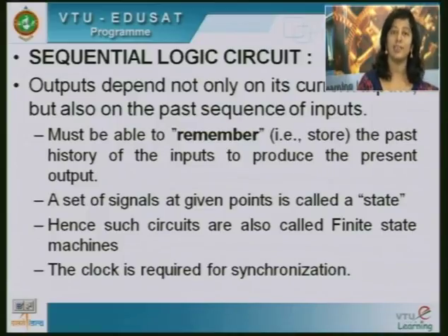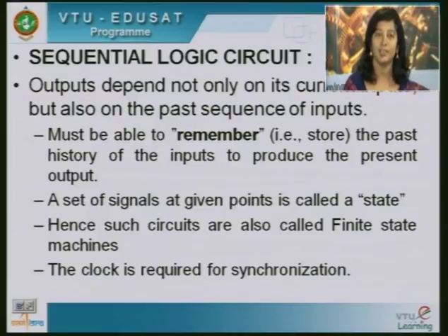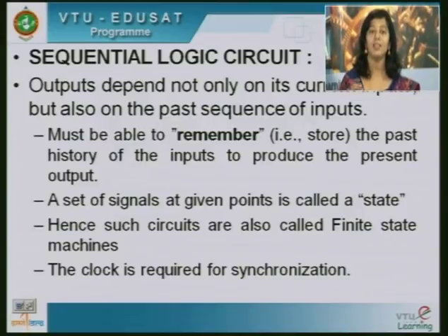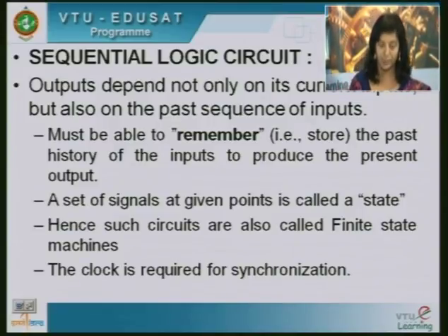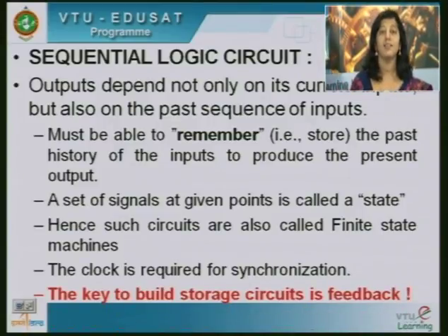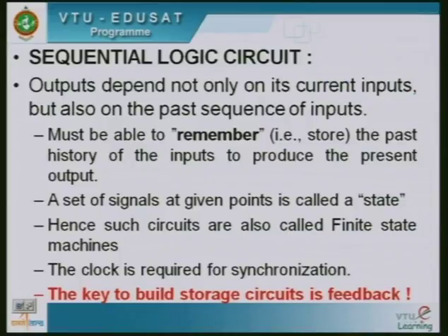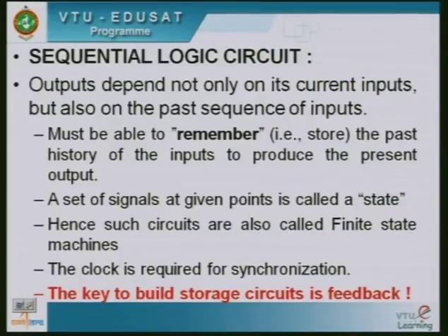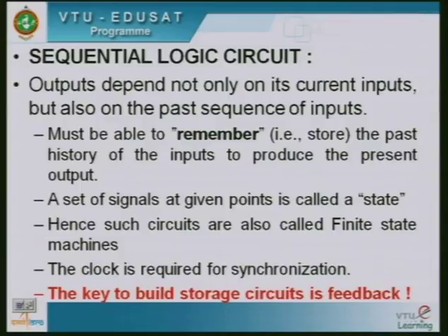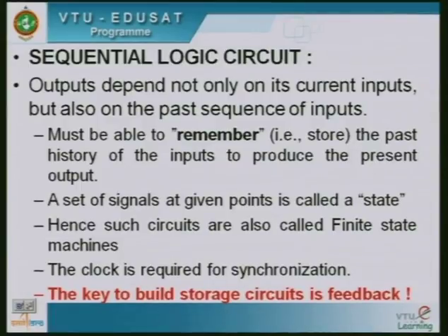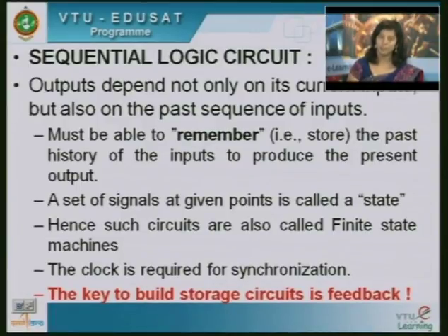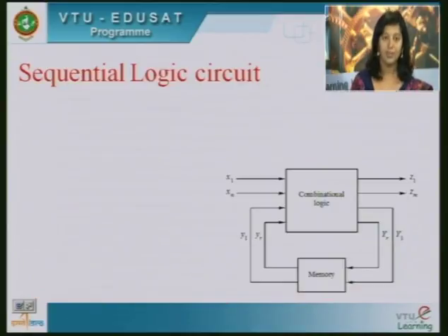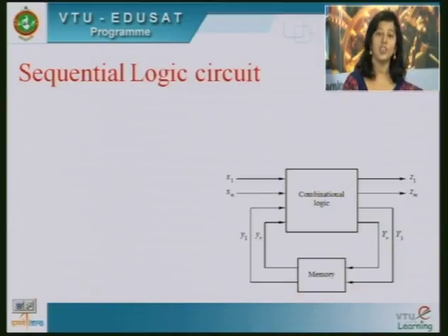We can have both asynchronous and synchronous forms of the circuit, but usually we need a clock also for synchronization. And just remember this, the key to build memory or the key to build storage in the circuits is by using feedback. So, if you use feedback in your combinational logic circuit, you will be able to incorporate memory into the circuit. Let us see how a sequential logic.